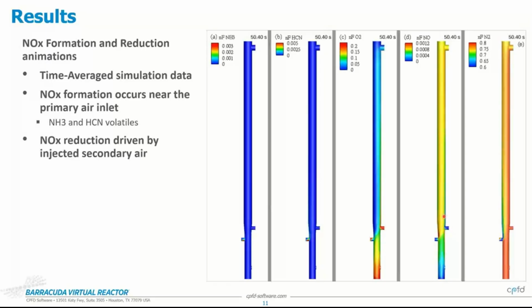So you can see that it goes from yellow to green to bluish over time, pretty much. However, the unfortunate thing is that, at least looking at these results initially, it seems like the penetration of the secondary air inside the reactor is not happening very well. So the oxygen comes in, but if it's not penetrating deep enough into the reactor, it's only able to reduce the NOx more towards the side of the wall down here, and you do produce nitrogen over that side essentially. But ideally, if this can penetrate deeper inside, I can capture more, or I can reduce more of the NOx gases.